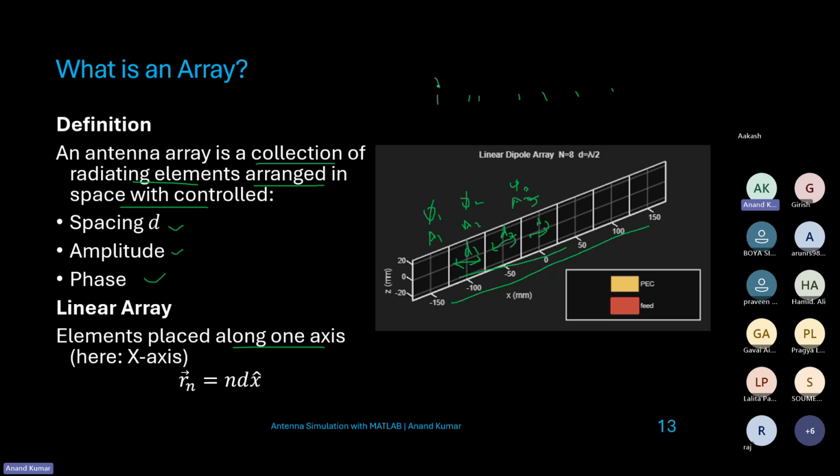They could have different amplitudes as well, or the same amplitudes. They could have different phases, which is used in beam steering. So all these things you can actually do, and if you are able to make an array with a circuit such that you can control all these variables, you can do a lot with that. You can keep changing patterns based on your requirement.